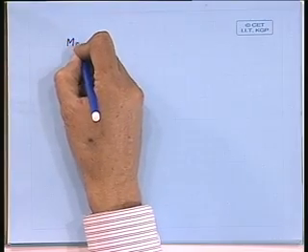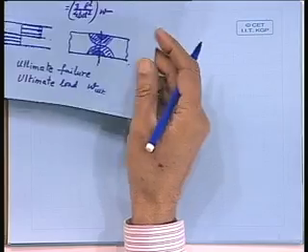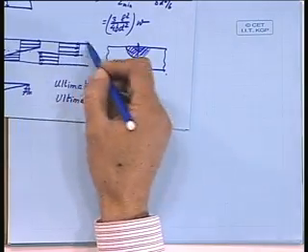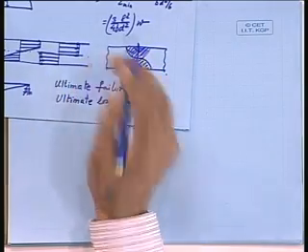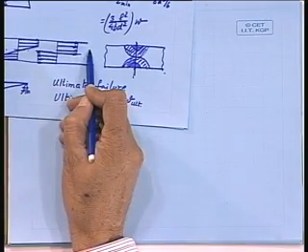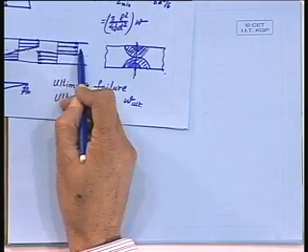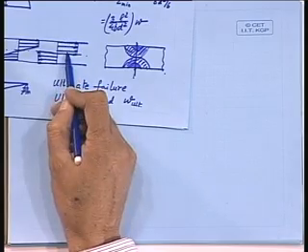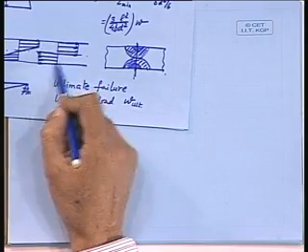Right. Now with this type of stress distribution, what is the moment here? So let me write in a very simple manner, MP is equal to what? Plastic moment. This has become completely plastic, so what is the moment at this stage, just before collapse? This is sigma y all through, this is also sigma y all through.